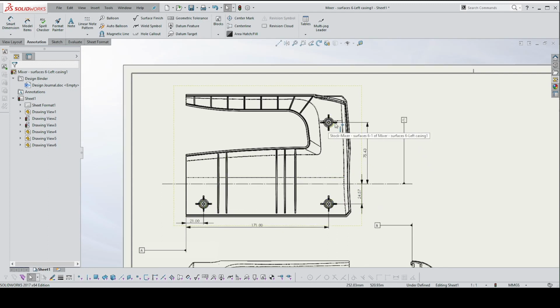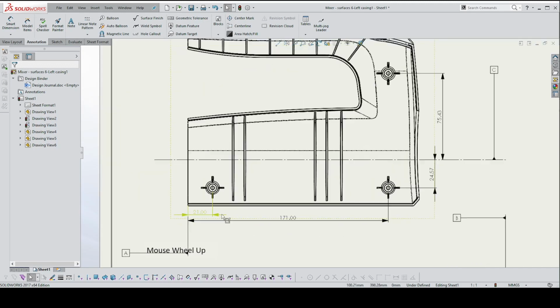Just the positions. That's what we want first. These are the most important dimensions, not the size dimensions, the position dimensions. They're all important, but these are the ones you have to have first, and I look for first. And if you haven't got them, that's where you lose the most marks. Putting size dimensions in is easy. Figuring out how to put your position dimensions in is a little bit harder, and that's where the intelligence comes in.